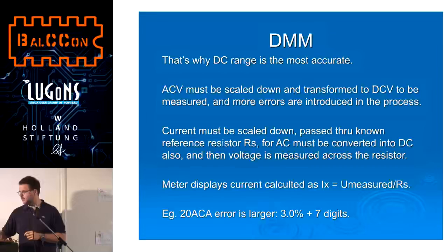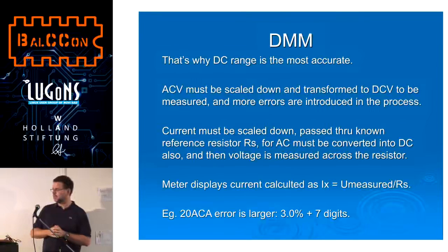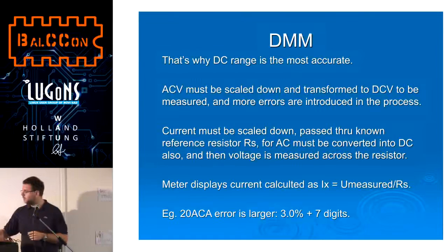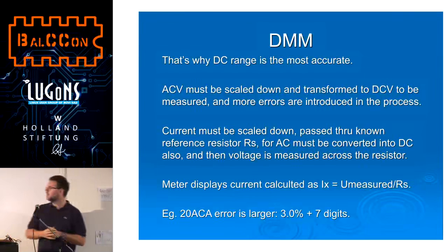If I'm going to measure 2 volts, first I have to divide it by 10 and measure it. If I divide the voltages up to 2 volts by 10, I get 200 millivolts, etc. High voltages have a 10,000 scale down factor. The most accurate readout is at that basic range.